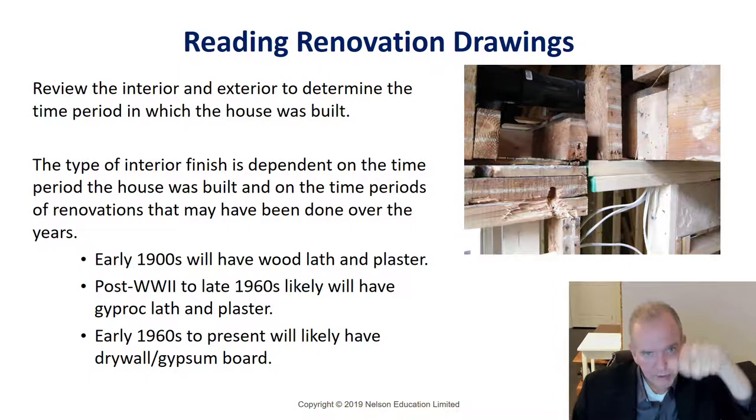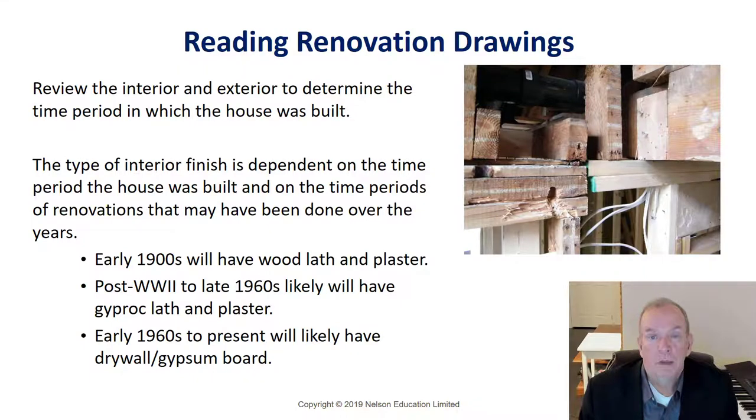And the putty coat was this nice white lime that was basically slaked. And slaked is that it was allowed to sort of percolate overnight and become a very smooth kind of cream that would be troweled on and give a nice finish to the actual wall. It took artisans to actually trowel that on.